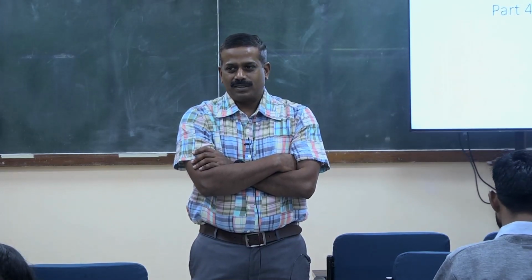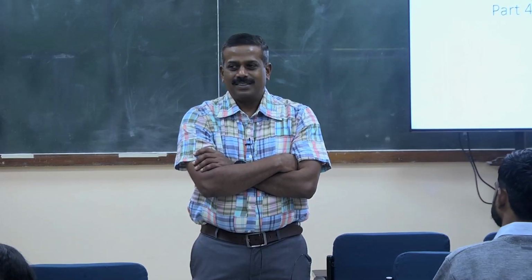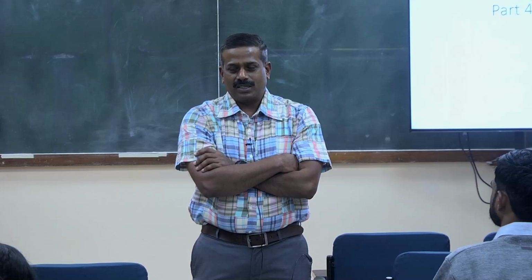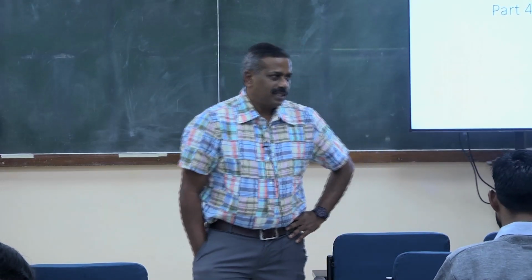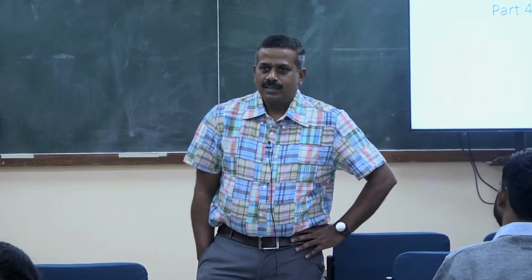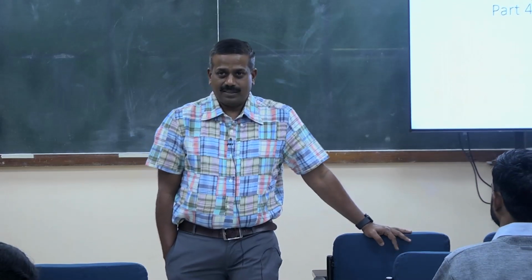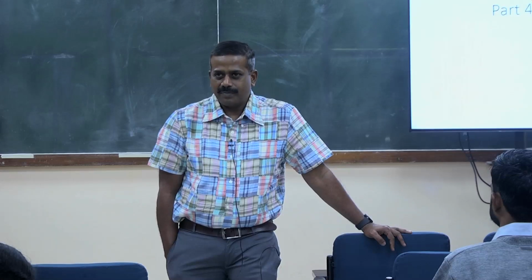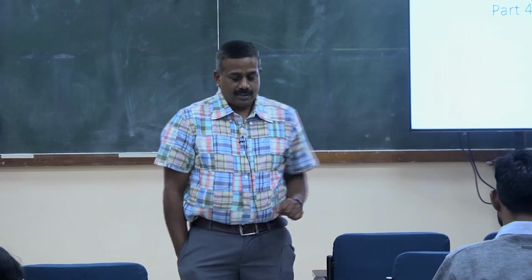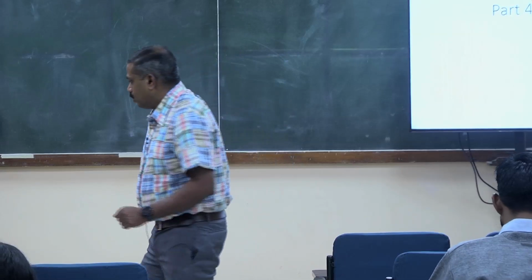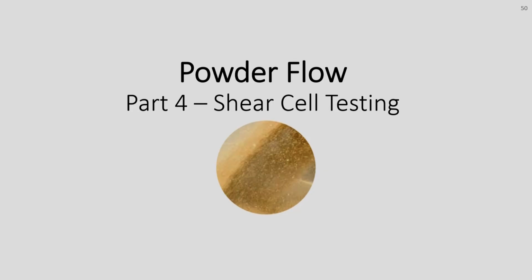One more thing, the last thing before we ended. Rheometers, yes. So powder rheometer, right? Especially, we talked about the FT4 or Freeman Technologies powder rheometer, right? So we talked about basic flow energy, specific energy, aeration, permeability, etc., right? So again, whatever methods that we talked about yesterday, most of them are traditional, qualitative indicators.